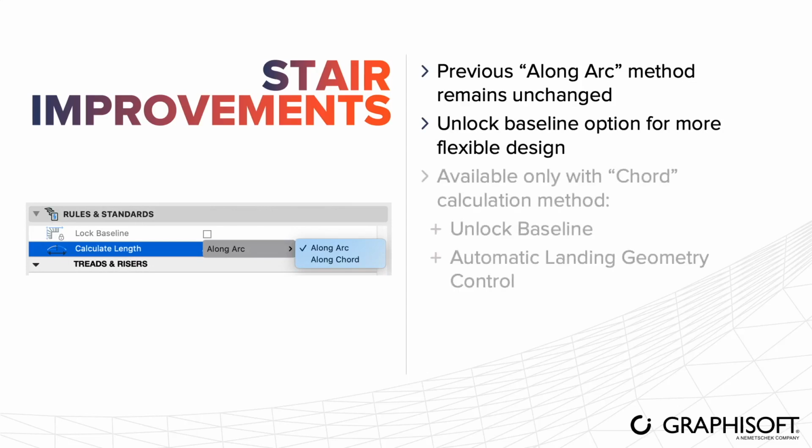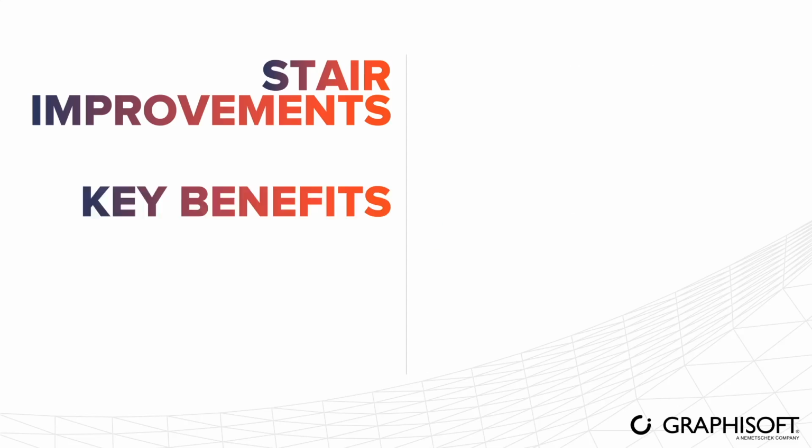And there are also some new functions which are available only with the Chord calculation method, which are the unlock baseline and the automatic landing geometry control. To summarize, the stair improvements bring more flexibility when designing, and also all these improvements will allow stair projects to be compliant with specific local standards.